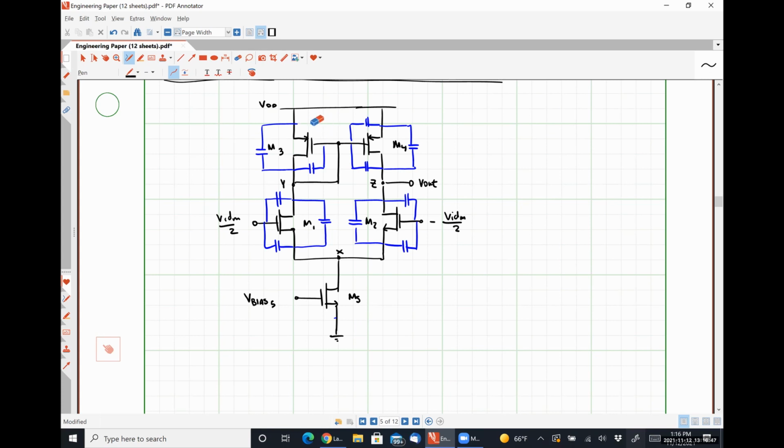So I'm going to say that we can throw all of these guys away and replace all those guys with a single capacitance CY, which is just the output capacitance for the left-hand side of the circuit that we dealt with earlier, right? So we know how to find it. This is just a shortcut. And we can do the exact same thing on the right-hand side here, right? We know that none of the capacitances on the input side really affect our frequency response whatsoever.